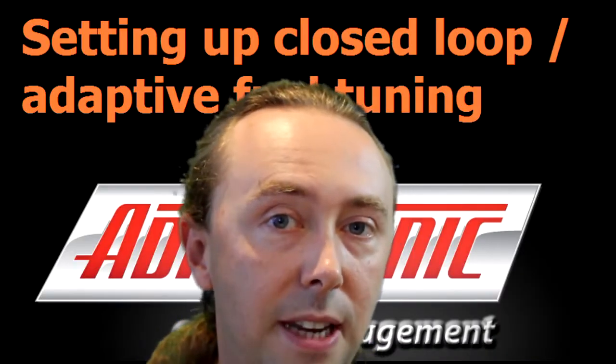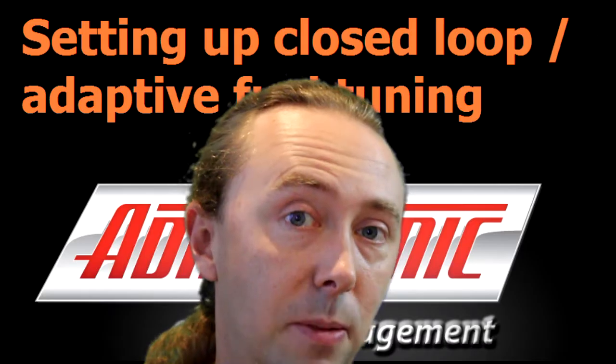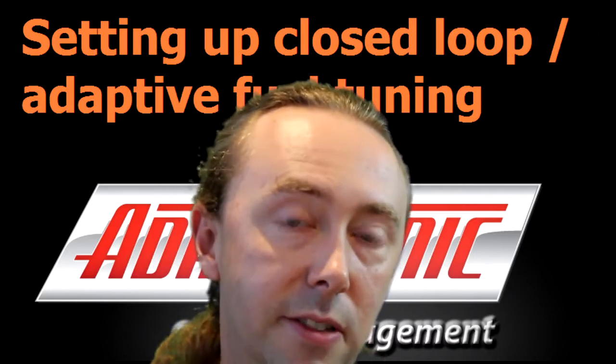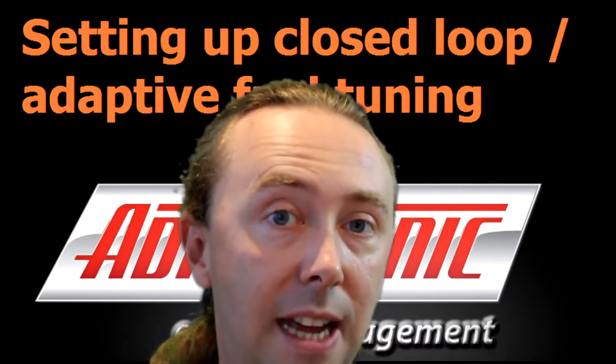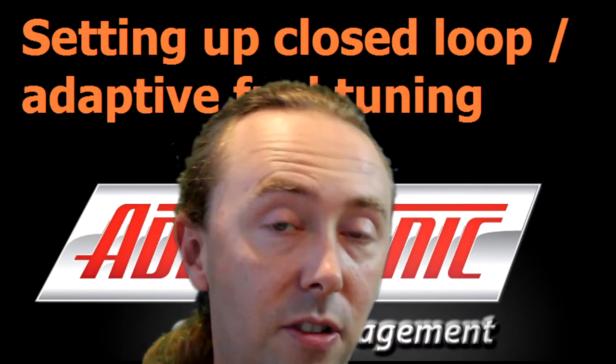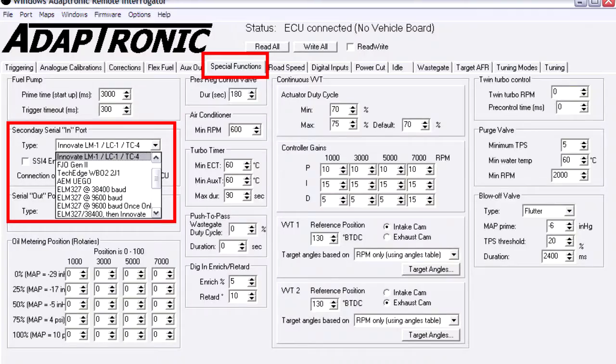Now a lot of cars come with a narrowband O2 sensor, which is actually very accurate around stoichiometry, which is lambda 1 or 14.7 to 1 air-fuel ratio for gasoline or petrol, but outside that range it's really not very useful. So you can use that to run closed loop at cruise and idle, where you'd be wanting to run 14.7 to 1, but if you're trying to run a different mixture, then you can't really use it. You need to use a wideband sensor. A wideband sensor allows you to run the closed loop fuel control for the entire range of the sensor.